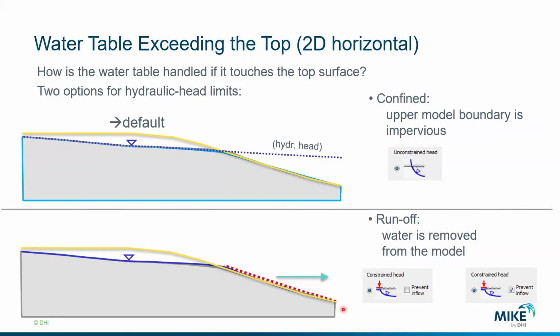You have a rise of the water table due to some events, and infiltration in other parts of the domain. So the water table is rising like this. If you would like to estimate what the flooded area will be, you can also use this approach, and how much will be discharged to the overland could also be estimated by this simplified approach.